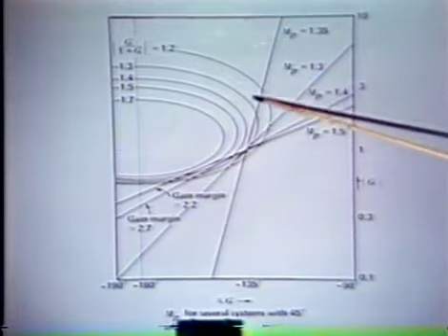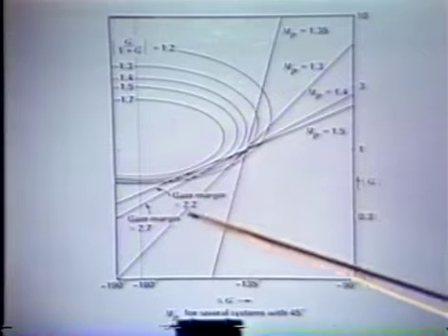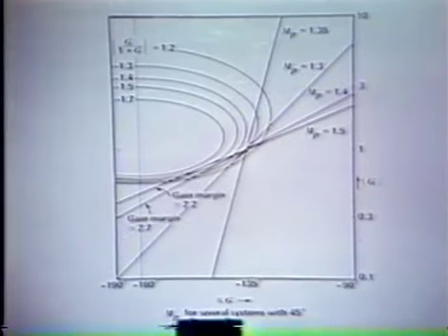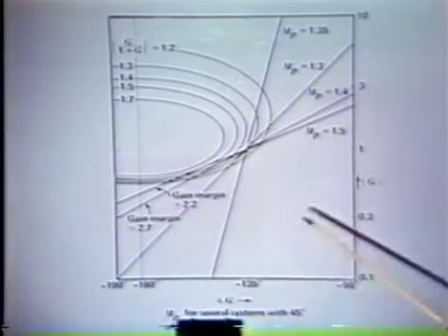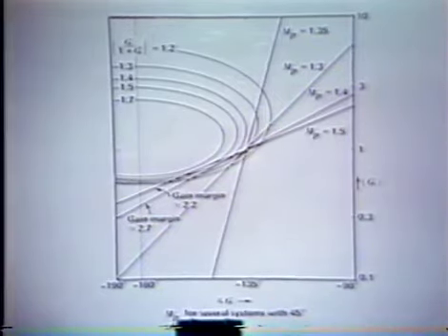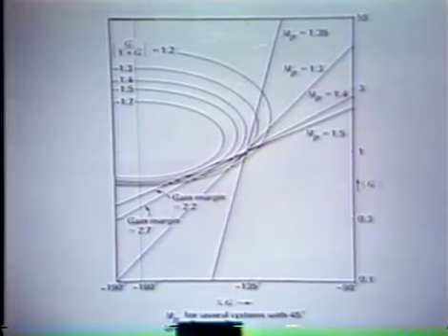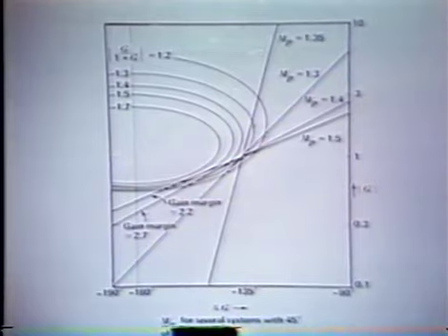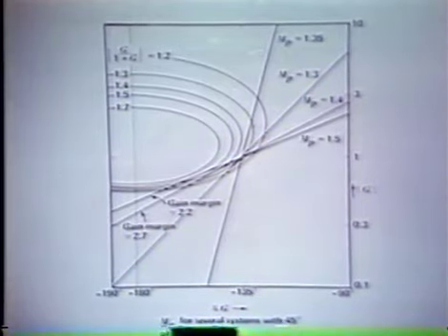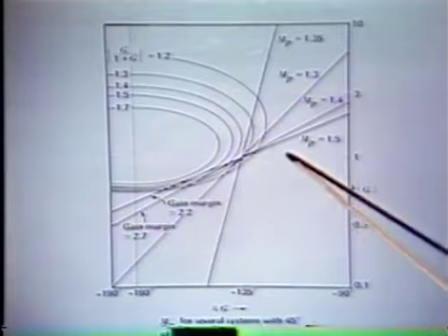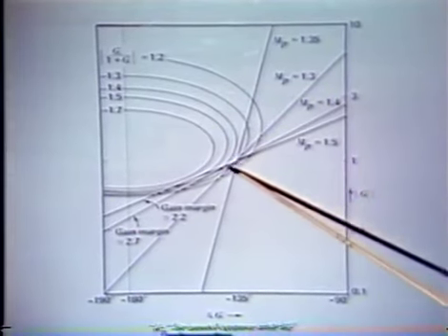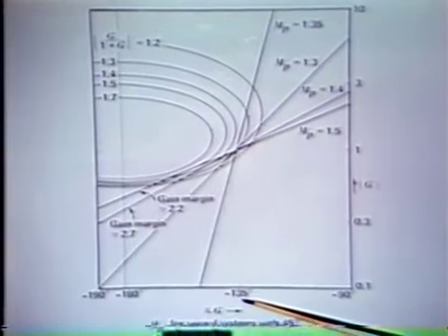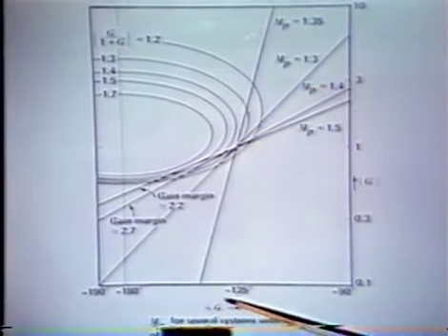So here are several possible AF products with different slopes in the gain phase plane. And what I'll assume is that, or we'll do the construction such that all of these AF products have phase margins of 45 degrees. That says that they all go through the point magnitude of AF equals 1, angle of AF equals minus 135 degrees. This distance then is 45 degrees.